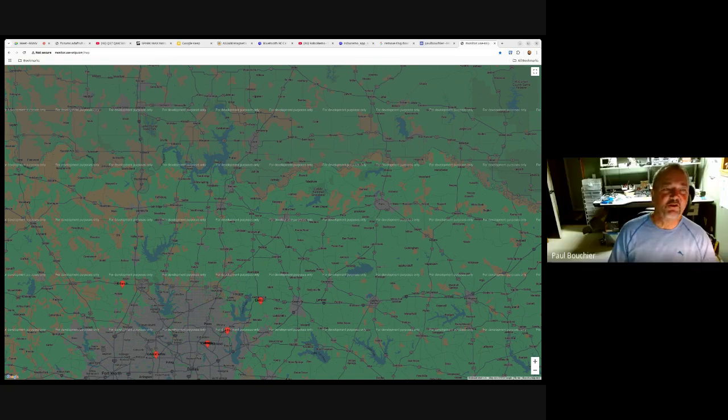Yeah, but that's not what they do. They turn it on for 24 hours and then average the fix over 24 hours. And I don't know of any way that you could assert that over 24 hours the scatter plot that Tom showed would actually be centered on your true GPS location. The assertion is that it is, and that's the basis for what they declare to be the location of the base station. But can you really count on that?